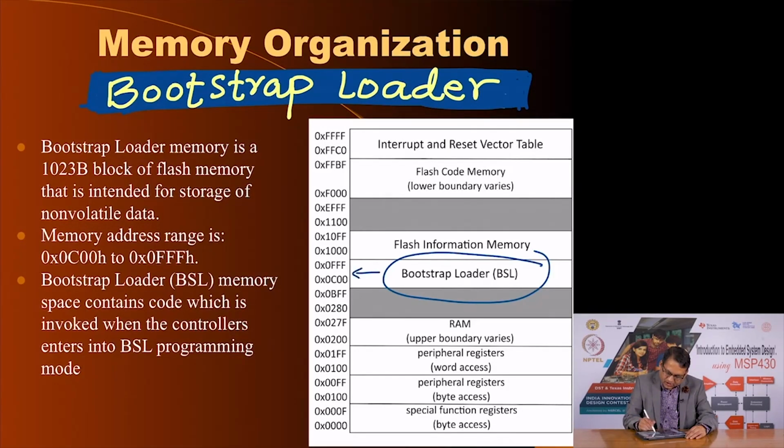This is the location, and in the case of MSP430 microcontrollers, you do not have to write that program. Each and every MSP430 microcontroller, especially the G series, comes with a pre-programmed bootstrap loader. All you have to do is provide, in your microcontroller system, an ecosystem which is compatible with invoking the bootstrap loader mechanism, and then you can upload any program from your desktop computer into the memory of the microcontroller. Later in this section we will discuss that.